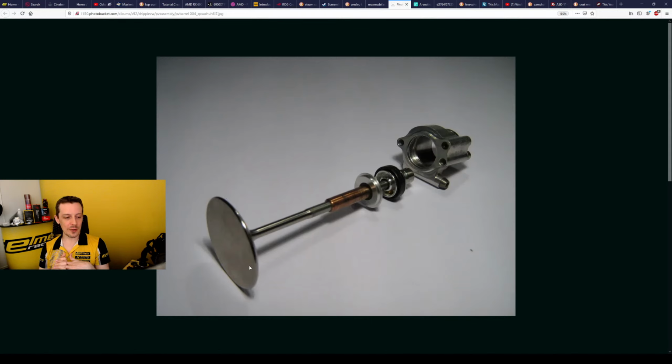So you do see those, but manufacturing of sodium filled valves is being ramped down now. Last I checked, you couldn't even custom order sodium filled valves anymore. It's just the designs that are already there and the manufacturing setup that is available, Supertech at least. I think there are probably some other manufacturers that also make these, but they're not doing new designs anymore, they're just using the current ones. I'm assuming that's because the Inconel alloys are good enough already, so you don't need to use sodium filled stuff. But the sodium stuff is still better.